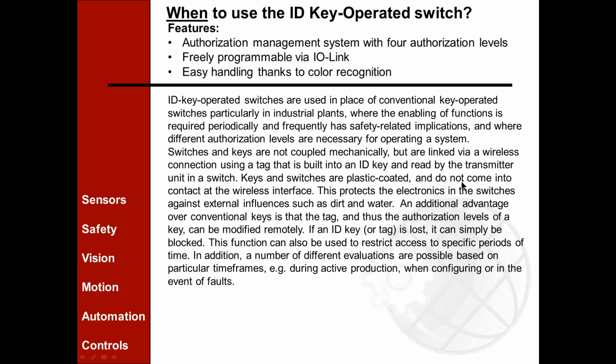The keys and switches are plastic coated, and don't come in contact with the wireless interface. So what this means is these are IP65 rated. Inside the actuator part, it is sealed again to IP65. It's dust proof, and I think it's equivalent to your old NEMA 12 ratings for people that remember that.